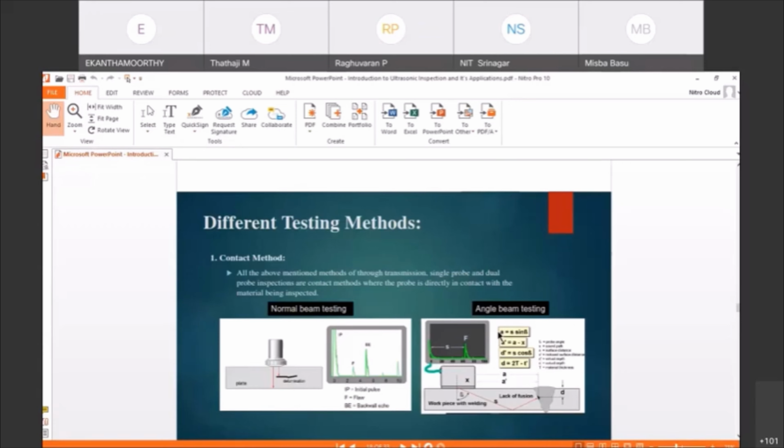Once you know the trigonometry, especially for weld inspection, you can apply it as per your area of interest. We can easily see how the wave is generated at an angle, and based on that we calculate the skip distances and in what skip I have to cover this entire weld. So this is one of the advantages of angle beam inspection to check the weld integrity.